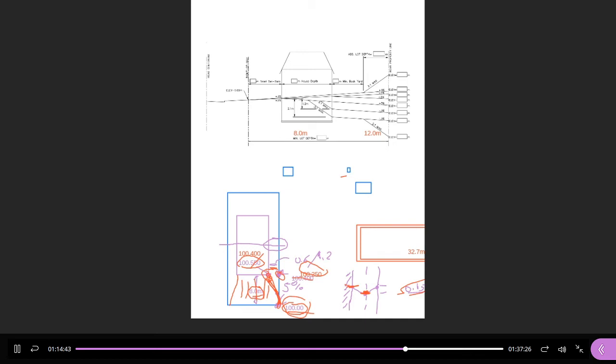So this is kind of the opposite scenario now. What if the existing ground was way down here? Then I would design this. I would start at the front, go up at 2% to the front of the building. Then I would lower the backyard by 2.1 meters to get the elevation at the back of the building. Then I would have the minimum usable backyard. And then I would come down at 3-to-1. And then the difference would be a wall.